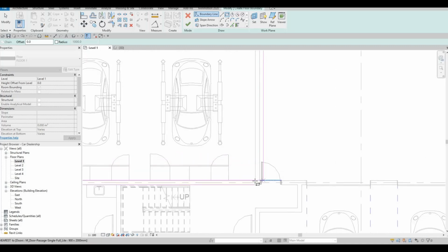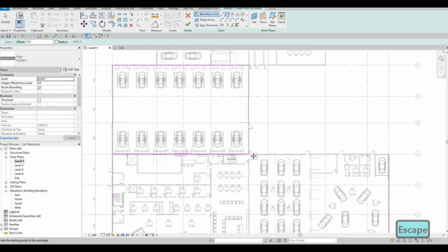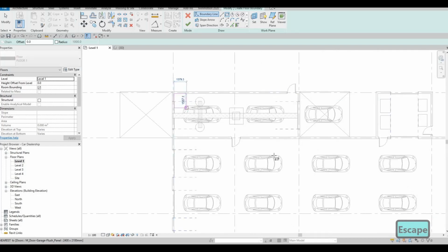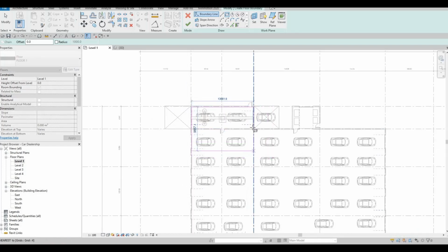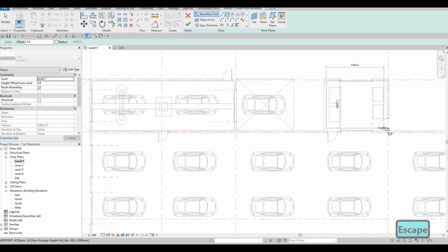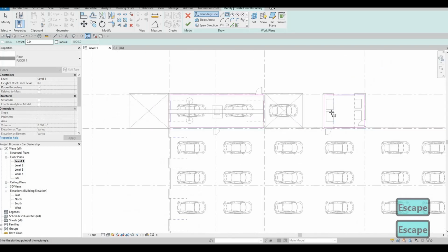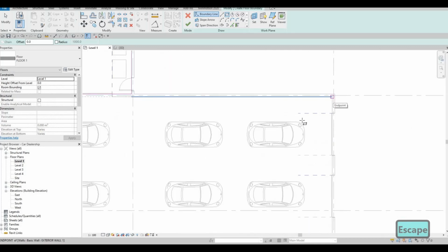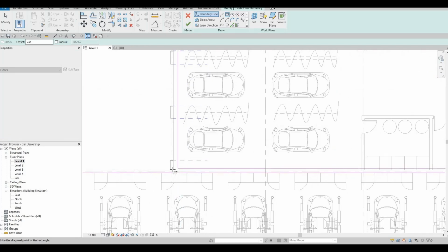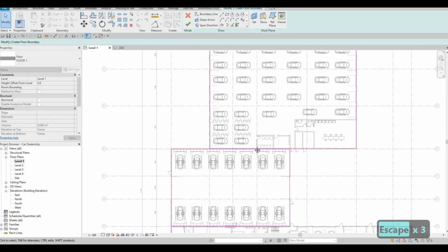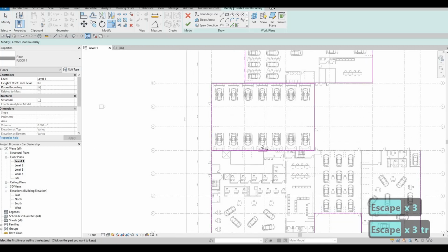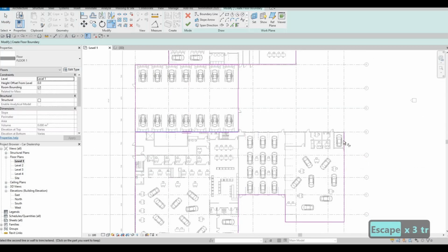So just one big floor, and then we can always change this later on. So that's how I usually add floors on this kind of big project. Everything's squared anyway, so might as well just add those and then trim it out later on.